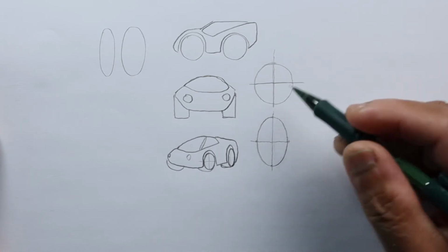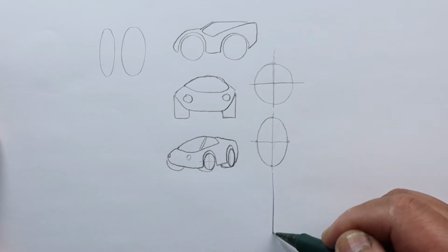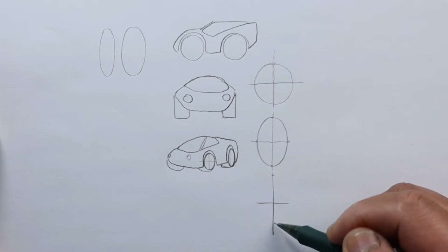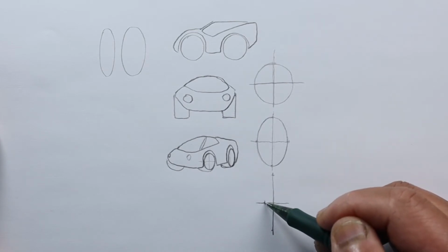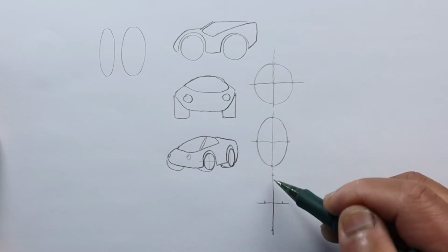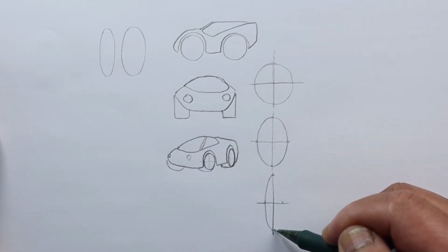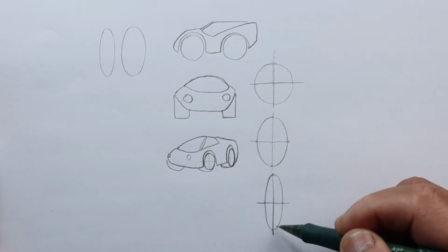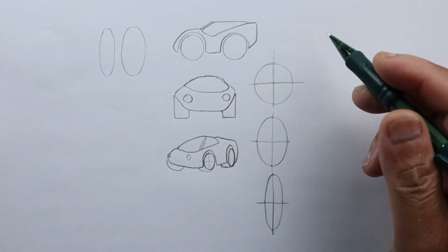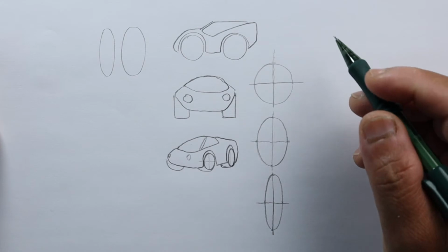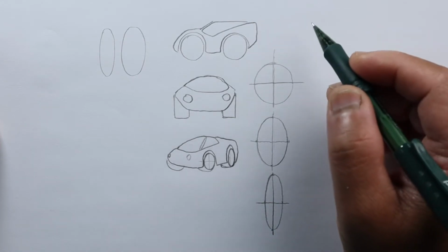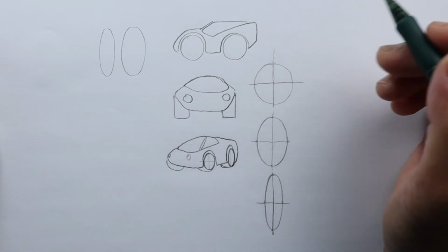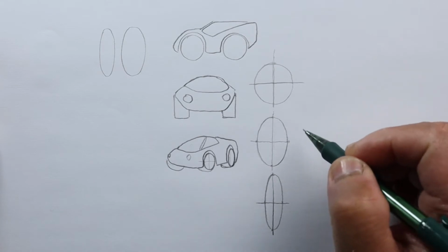The more this circle gets turned, the narrower it becomes. The short axis becomes narrower. So again, we'll make the height the same, but the short axis is much shorter. We'll connect these like that, and you've got a narrow oval. These ovals can also be called ellipses, and you can find ellipse drawing guides, plastic drawing guides, in order to be able to draw these exactly. For example, when you're drawing something that's very technical and you want it to be super accurate.